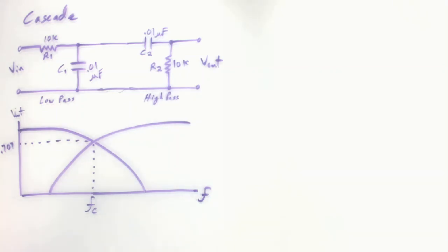So lots of ways to do it. We'll take the simplest way, and it'll lead us right into a classic circuit. So what is a bandpass response? Well, we said there's a band of frequencies right in here that will have a chance of getting through this cascaded low pass and high pass. So it is a bandpass response.